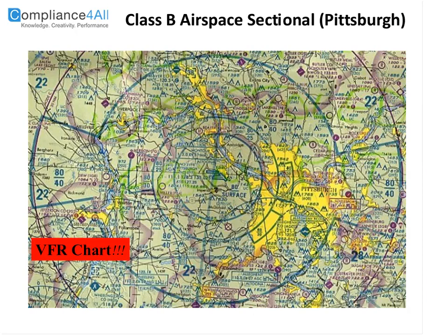So in addition to all that, now remember back when we talked about the VFR traffic and how as traffic builds and builds, the VFRs become more and more risky to have flying around, not being controlled by ATC, so they put in more restrictions. And this is a thing called Class B airspace, which is near Pittsburgh. Class B airspace means that if you want to enter it, you have to be talking to ATC, okay? And you have to follow directions and maintain altitudes and basically operate as if you were an IFR qualified pilot.